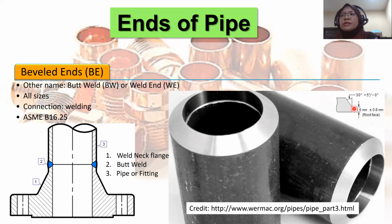This one is beveled to an angle of 30 degrees with a root face. This is the root face around here, a root face of 1.6 millimeter. It has a specific geometry, and this is specified under ASME B16.25. So this is an illustration of the pipe end with butt weld, or we call it beveled ends.